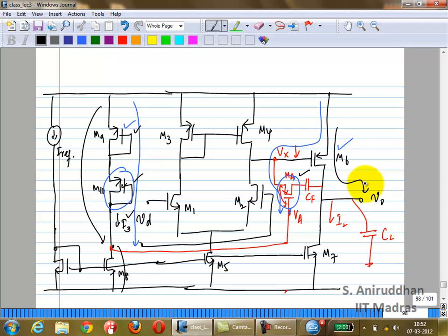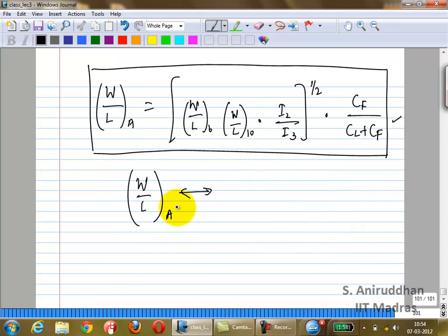Okay. So at that time that is true, but that's okay. Slewing is a very nonlinear phenomenon. Okay, and if it doesn't track, you can't do anything about it. What you are worried about is that this thing tracks very well for small signal cases when the op-amp is used in linear operation. So this is one case where we try to generate an RF based on 1 over GM2.